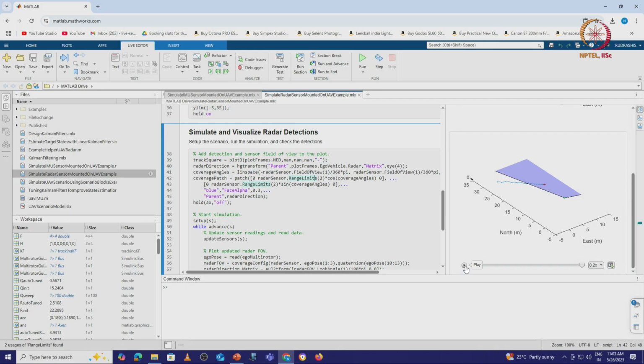So, what will happen is once we get the completely integrated system, we will be able to validate the controller design we have done or the autonomy algorithm we have done for obstacle avoidance. We can validate it and that can be integrated. This will reduce the fine tuning required in real world environment, because there is a lot of uncertainty present in here. If we can model those uncertainties directly, we can reduce the time required to tune the algorithms for practical demonstration.